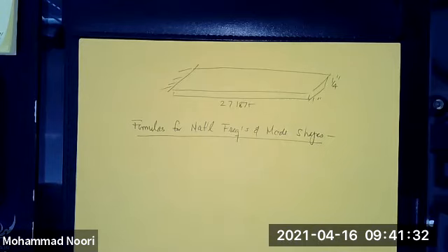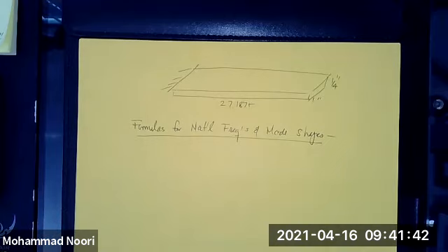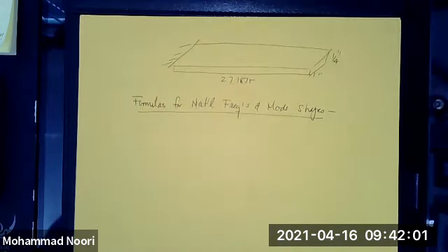And using the mechanical vibration of continuous systems, which takes you to all kinds of interesting partial differential equations, that's actually a course in itself, he evaluated the exact natural frequency and mode shapes of all those simple structures and tabulated those. They're available now online. You can Google it, find the natural frequency for a cantilever beam or a simply supported beam.